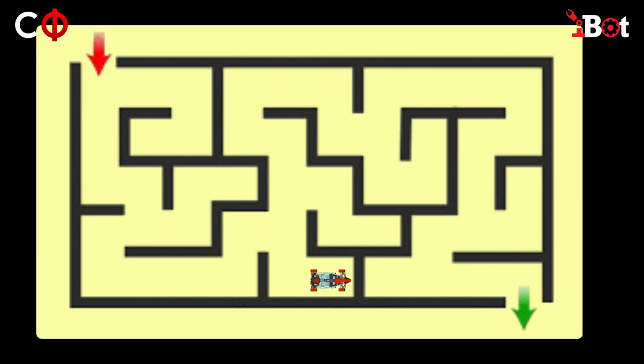So here it takes two left turns. That is because I have coded it so that when it senses an object on all three sides, it makes a left turn. Now it again detects a left turn because right is unavailable, so it makes another left turn. In that way, it makes a complete U-turn. In the next loop, I made it so that it completes a U-turn basically. It turns around here, a complete U-turn. In reality, it just turns two times right.